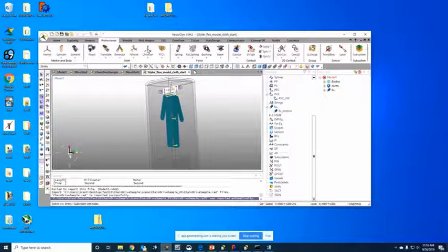In order to do this, we'll do a similar process to what I did in the previous example. The first thing that you would typically do is make sure that you had saved the XML file in a certain location, and you also need to confirm that RecurDyn knows the path for the Particleworks solver.